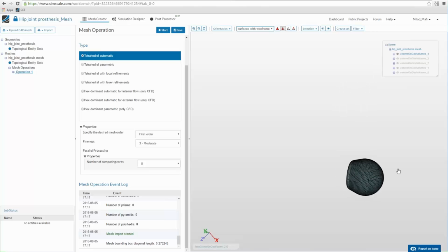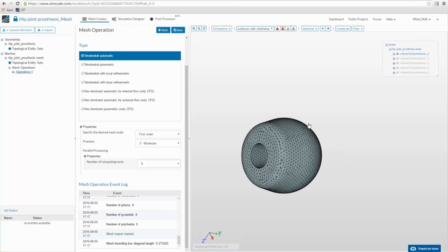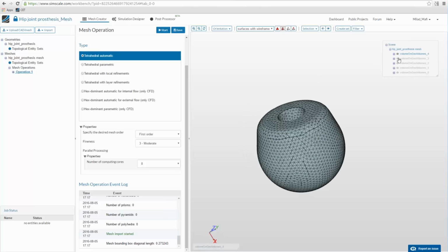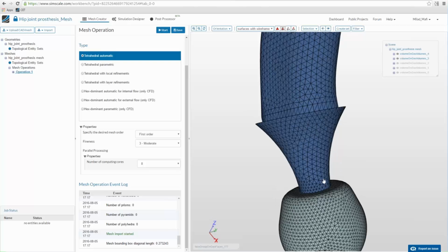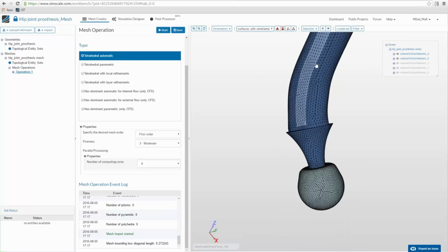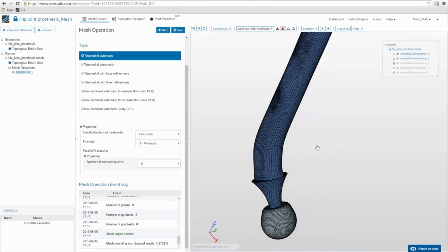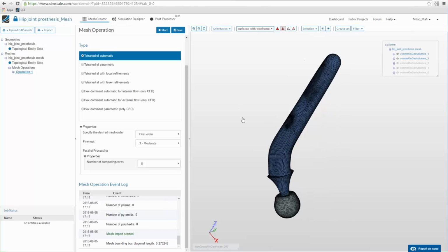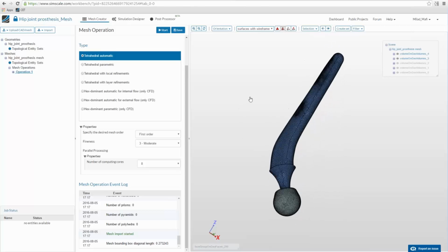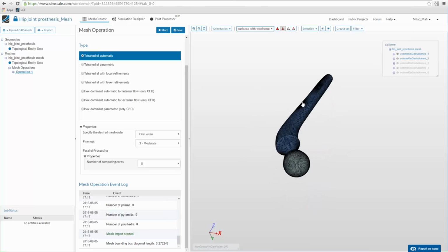And for example, now you can see this femur head was automatically split up into smaller cells, and you can also see that the cell size was automatically adapted. So we have smaller cells here where we have this contact between two parts, and larger cells far away. And the reason for this makes absolutely sense, because only there where we think we will have high changes or high stress, only there we need a fine mesh. And therefore, based on intelligence, the tool automatically refines the mesh there where it thinks you will have high stresses, which you want to resolve.